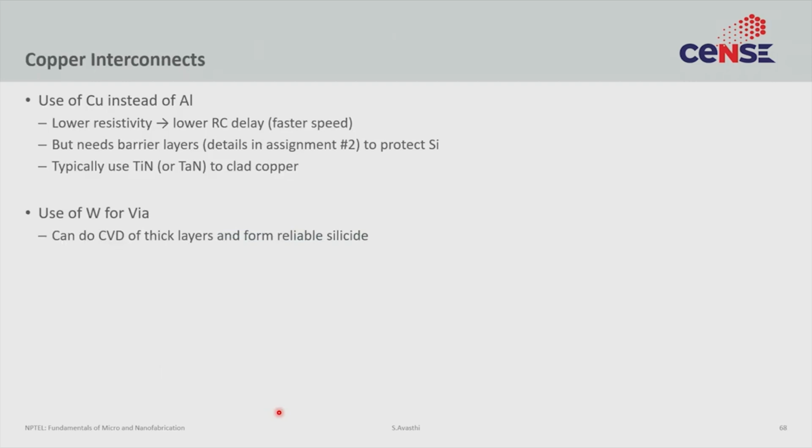After electromigration, another very important aspect to discuss is the industry's movement to copper from aluminum. Aluminum has great things going for it. It's low cost, and it can be deposited through several different techniques fairly easily. It forms relatively good contacts with silicon. Due to anneal, it creates great interfaces. It has very low resistivity, I think the third or the fourth lowest in the whole periodic table. All of this is great.